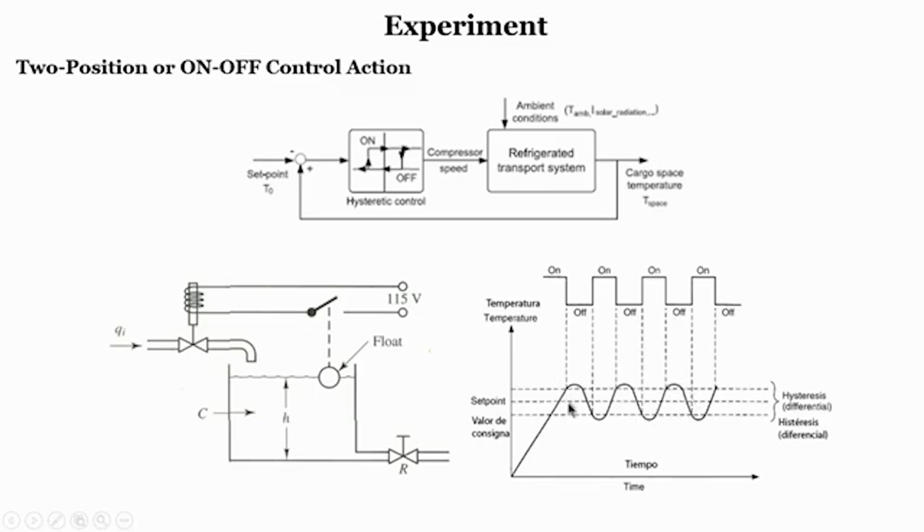As long as this range is okay, we can go with an on-off controller. So, it is clear that an on-off controller is not really controlling; it is on and off, on and off, depending upon the variation in your input based upon the set point.